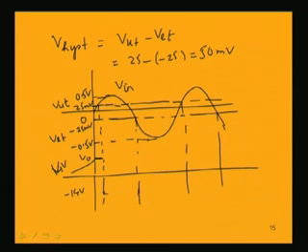In between these two it will be varying, and we will get this type of waveform. Of course, this half and this half are equal, the drawing is improper. So, these two halves are equal. We get a square wave between plus 14 and minus 14 volt with this example of threshold voltage and the resistance values.